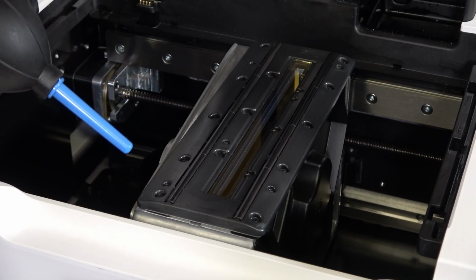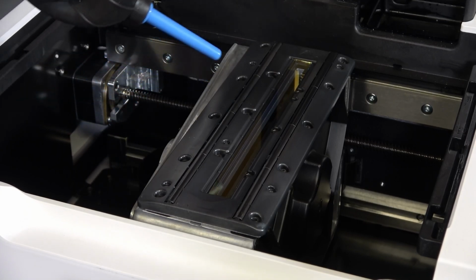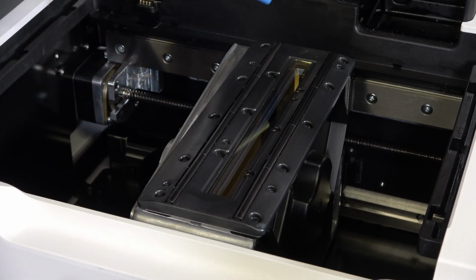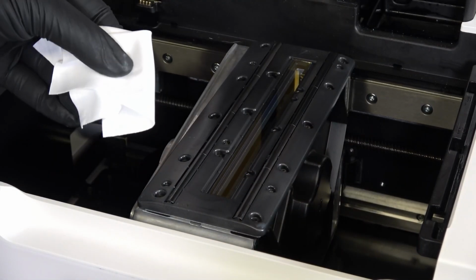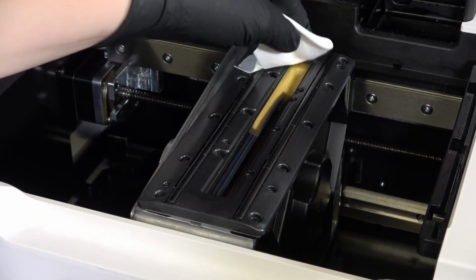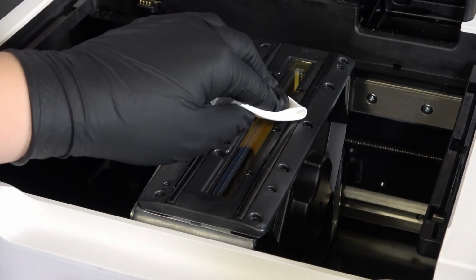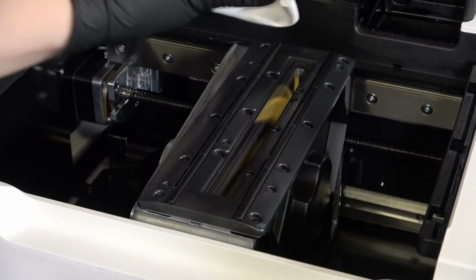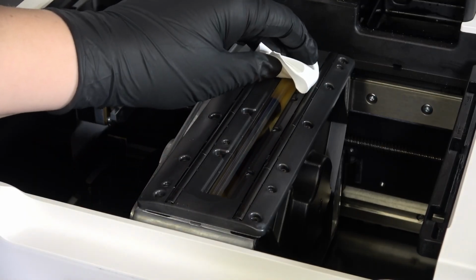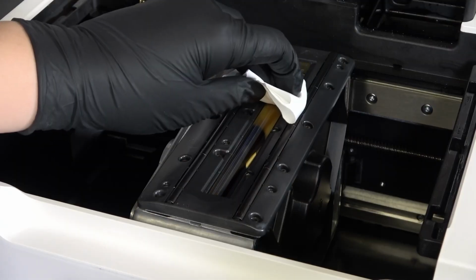Any of the following factors, or a combination of them, can cause non-adherence in prints. Printing without a raft, when the part has no suitable flat surface to grip the build platform, debris, clouding, or damage in the resin tank weakening the printer's UV light, or contaminated optical surfaces weakening the printer's UV light. If the layers of the print are separating from each other within the part, and the raft is still attached to the build platform, the printer is likely experiencing another print defect such as delamination.